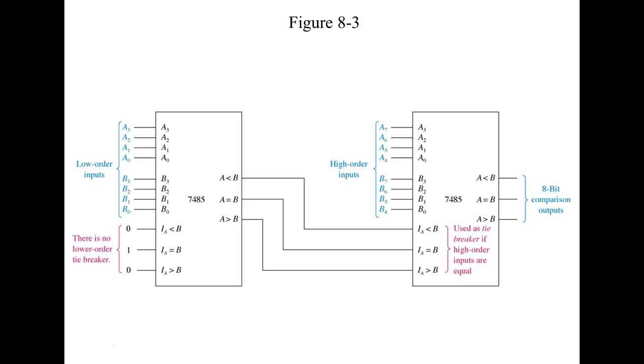So what the machinist would do, he would go on the panel and he'd enter, where he had thumb wheels, where he wanted his mill to go in reference to 0, and he'd press a button. And that's all it was doing, comparing the counts coming off the actual machine itself to the counts that he put in. And when they matched, the thing would stop. But the problem was, it never matched because one of the magnitude comparators had gone out.